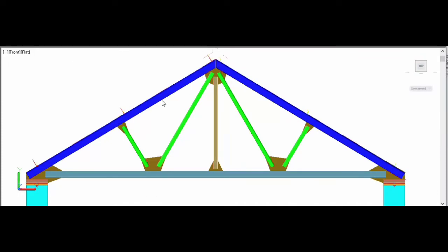So as said earlier, these are the principal rafters, which are normally compression members subjected to the vertical loads. These are the struts. The suspender will be subjected to tension. Therefore, this can be called a tie member. These two members will be subjected to tension. Therefore, this is also called a tie member. The bottom chord is also a tie member. We'll speak about all these tie members when I take up the chapter on design of tension members.